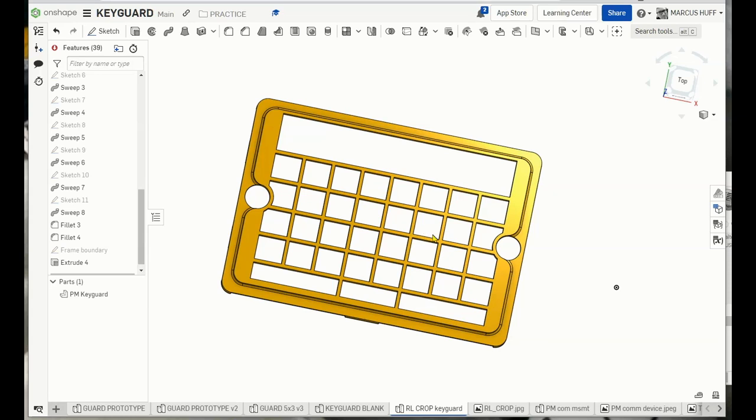This process could be streamlined a lot if you went through the sketch and deleted the lines that cross the intersections. Then this would be one continuous open sketch, and it would just be one single extrusion, but that's a lot of trimming. Since this is usually just a one and done thing, I just chose to click on all the little things, even though it was tedious.